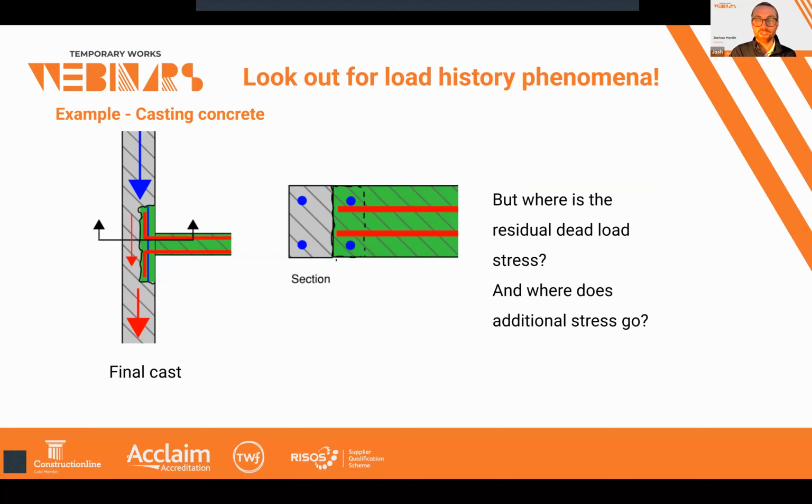Any additional loading onto the column from above or from the new structure that is applied after casting is therefore applied evenly over the grey and the green section, because that's new loading, okay? The new loading gets distributed everywhere. The old loading is only going through the older section. So the grey part is already taking higher stresses. Therefore, this activity of putting additional load on could push the column past its capacity.